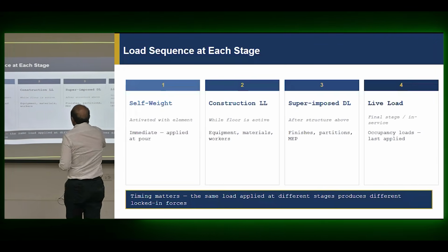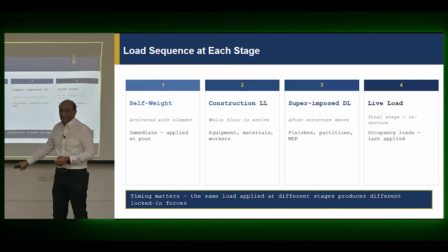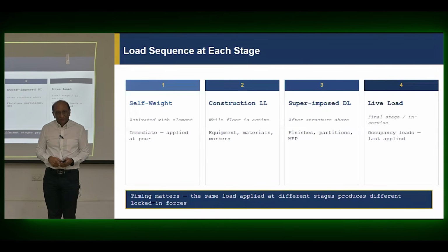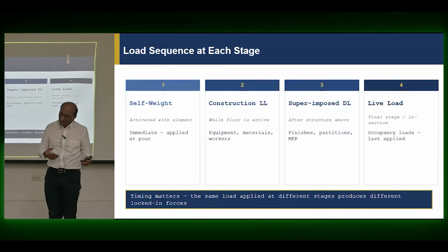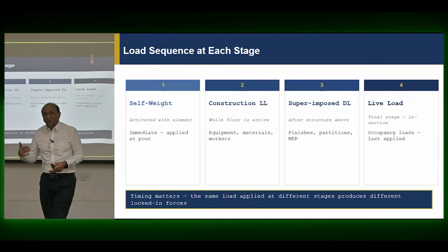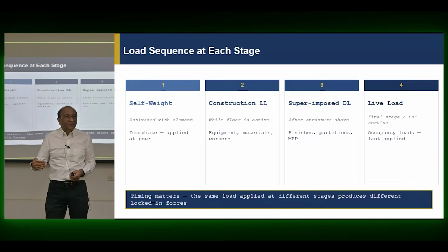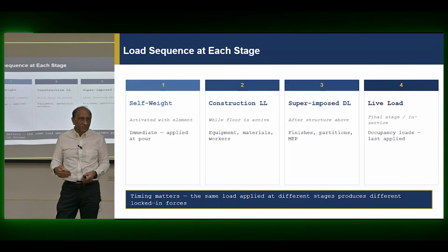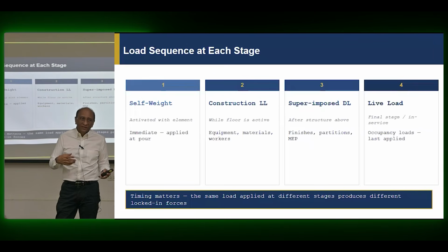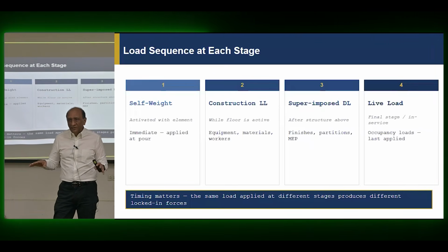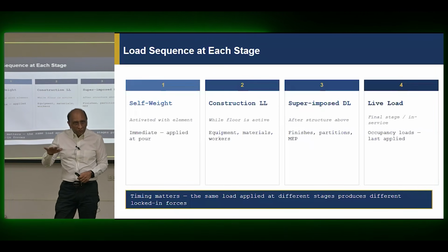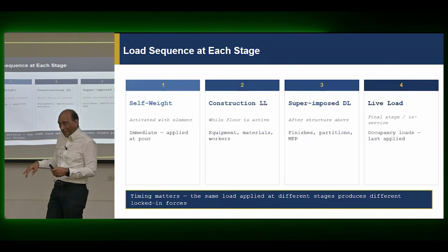Construction live load, which is happening during construction, is also important. And sometimes for bridges especially, and sometimes buildings, the construction load is also included in the construction sequence analysis, because sometimes it could be very high, very heavy. And sometimes the shoring, unshoring. So all of the live load during construction also has to be modeled or can be modeled.